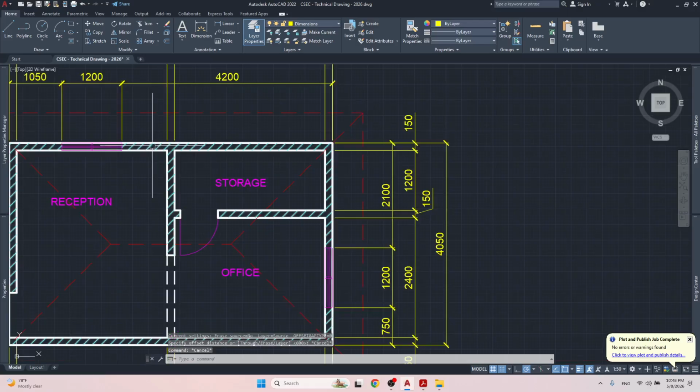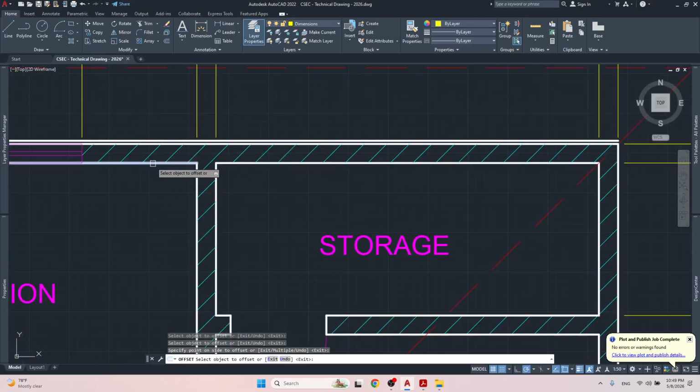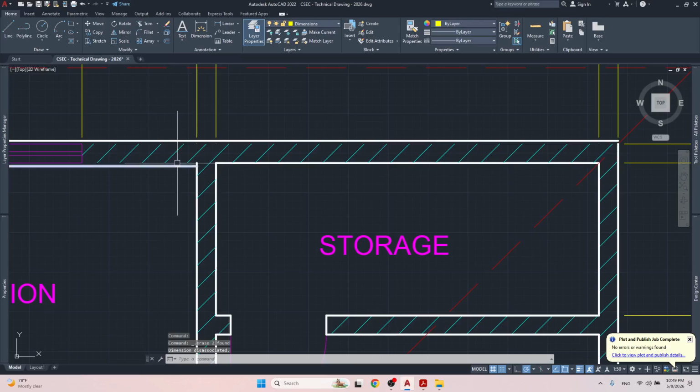These walls are 150 millimeters, 6-inch blocks, but for the foundation walls it would be 200 millimeters, which means I need 50 more millimeters of wall thickness. So if I distribute 50 evenly, it will be 25 on each side. So I would usually offset 25 on that side, and then 25 on this side, and then I would select the ones in the middle and delete them, and then I would have a thicker wall.